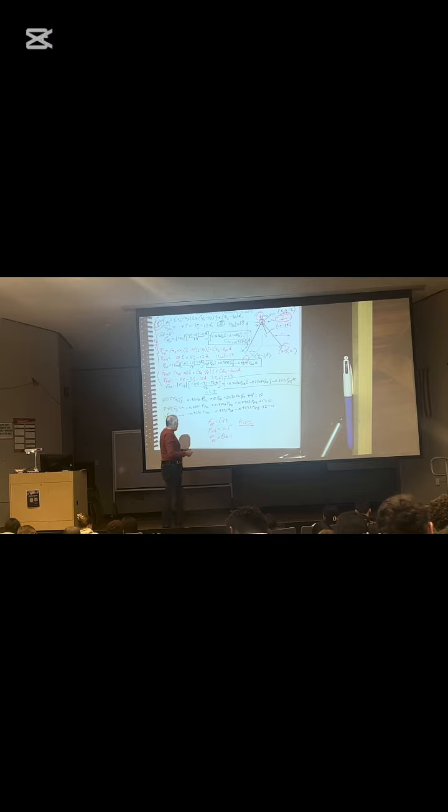Can PA and PC be cables? No, because cables can't push. They can pull, they can't push. So those have to be solid members, 2x4s or whatever. The other one, PB, you can put a cable in there and tighten it up to 6.5 kips.